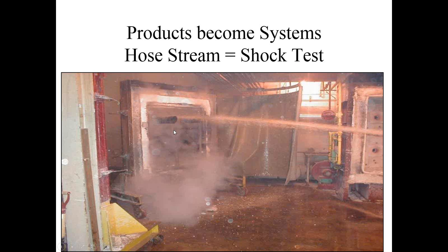The ceiling tile dropping and hitting it, ductwork falling from the ceiling as it breaks away from the breakaway connections to the fire damper, and hitting that penetrating item, jarring it hard so that if there's anything that opens up after that penetrating item got hit, the water hose stream will go through it and show up on the other side. The failure mode for that is if water gets through, it's a failure of the fire test. Even if they made it through the fire test and no flame poked through, if that hose stream shows water on the other side, guess what? You then fail that test.